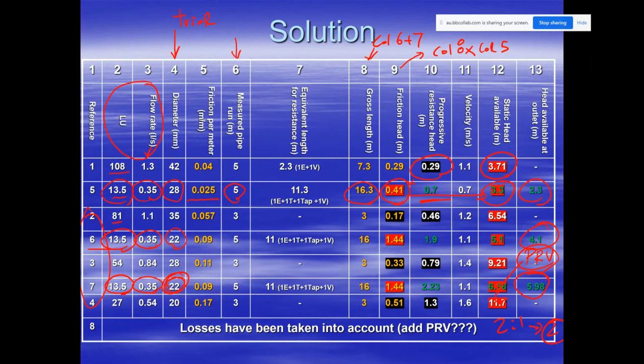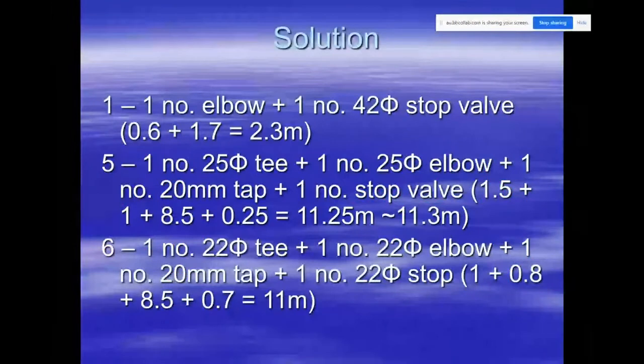You may say, sir, I conduct a very nice calculation, a very narrow range of discharge pressure, which I controlled. I will say, this is not good. This is not the perfect design because there is no flexibility. So the norm, 10 floors, 1 PRV. This is the experience from the industry. Understand? Okay, thank you very much.